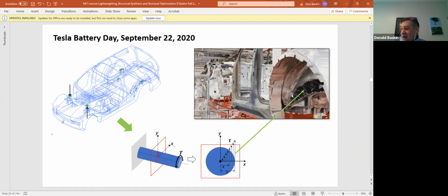And I think he brought up a really interesting example. He talked about airplane wings, and how airplane wings originally held the fuel, the kerosene or gasoline, whatever they run on, inside a tank inside the wing. And then somebody said, well, maybe we're using too much double structure there. So they combined the skins of the wing with the fuel tank, and they created a stiffer, lighter structure. That's pretty common in airplanes now, and in fact, I think it's pervasive. So this is a similar idea.